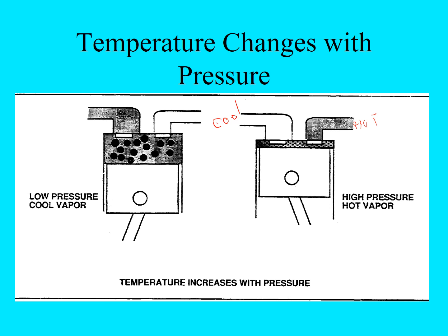We can't compress a liquid. If we did, we'd damage the compressor. Okay, we've had coolant leaks in the cooling system in a vehicle where antifreeze gets into a cylinder and the engine tries to crank over and it'll actually hydrostatically lock up. You can't compress that coolant.